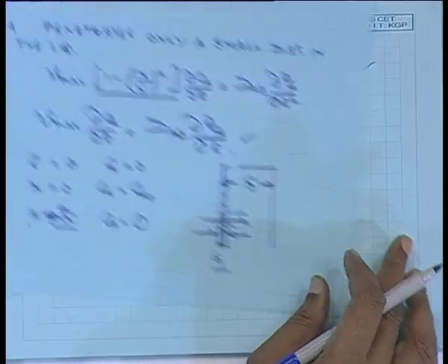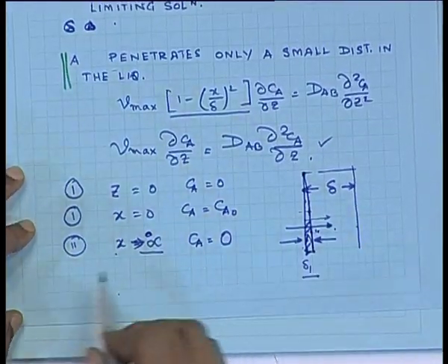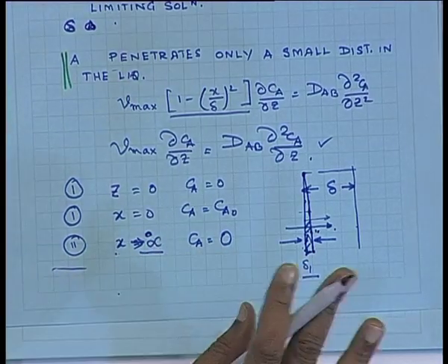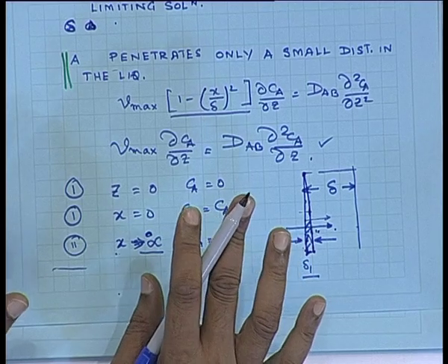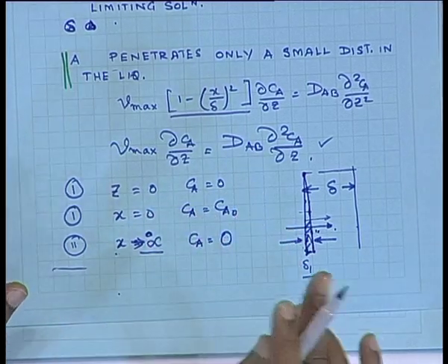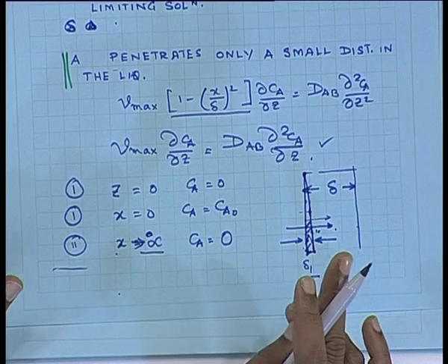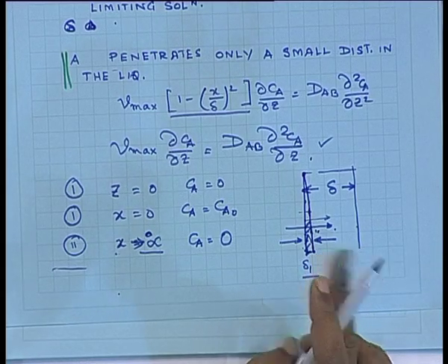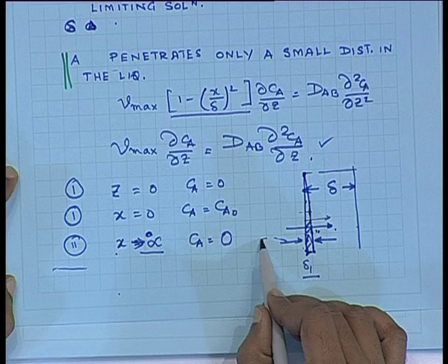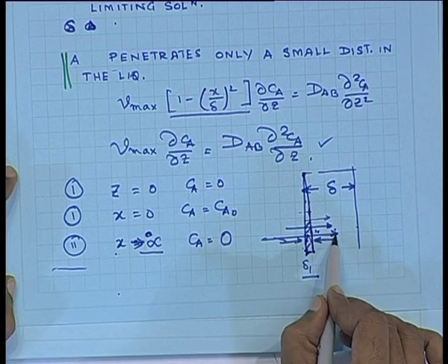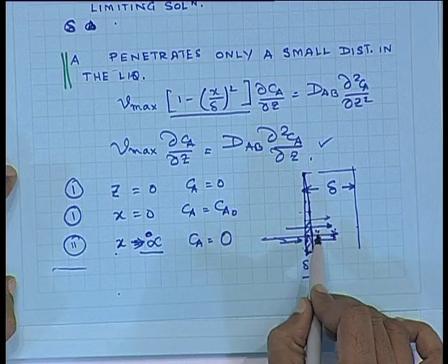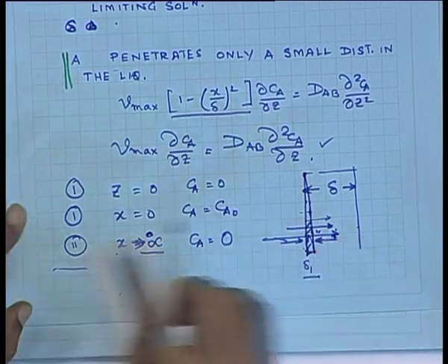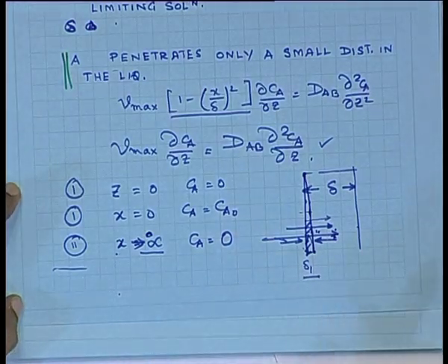All right. If we look back, the basics are clear. The mathematics you can look at in your textbook and follow. There is nothing in the mathematics, but at every point we should know the physical significance of the process. Motion in this direction is going to be enhanced by high diffusivity, and retarded by high viscosity. These two are at opposite purposes.